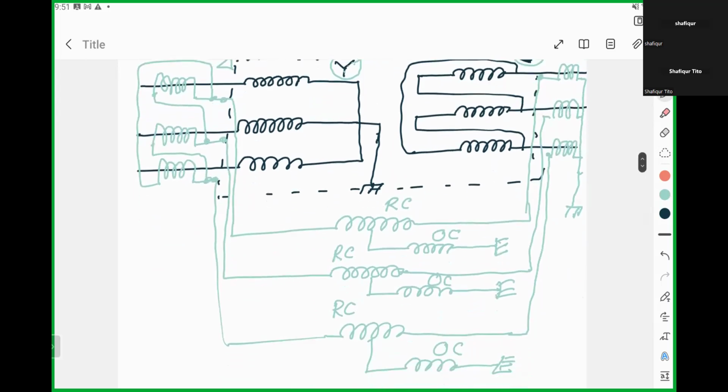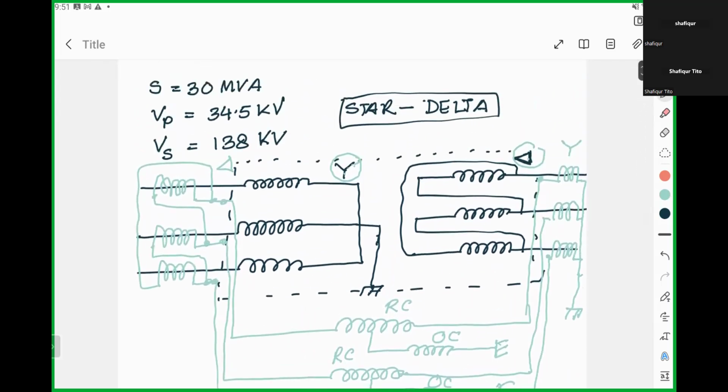And now we can identify the currents. Let us take a different color. Let us start with this one. So this is my primary side. The 1 indicates this is the primary side and this P indicates the primary current of the CT. So this current is flowing through this one, that is the primary current of the CT. Similarly, I can write I2P.